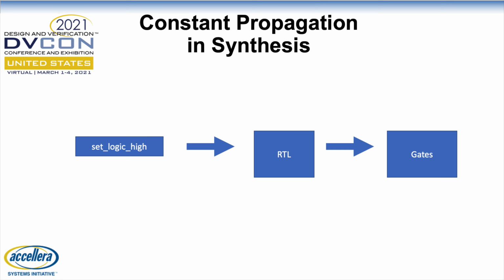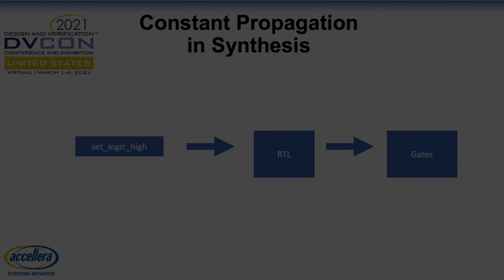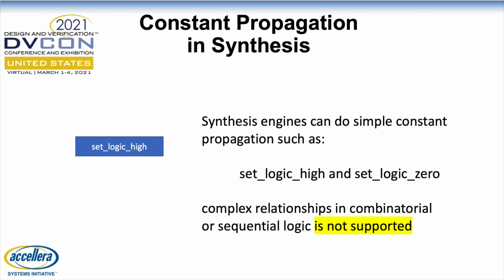And by doing this, when synthesis runs, it can recognize those constants in those Boolean equations it's trying to implement and use that to simplify down the logic. This is useful sometimes when you have a design where you can just tie one of the inputs to put it in a particular mode. And then when synthesis runs, it recognizes that mode, and that logic is propagated through all of the final gates of the design, and you get the design that you're looking for.